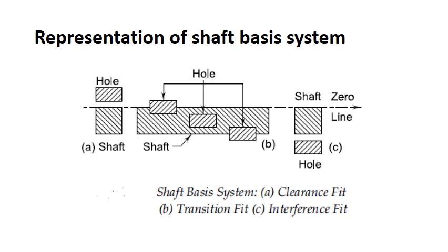Now can you see the shaft tolerance zone is touching the 0 line, whereas the tolerance zone of the hole is well above the 0 line. I'm going to associate the different clearances or interferences only with respect to the hole now. So first case, clearly we have a clearance fit. Figure A is clearance fit, and then figure C.